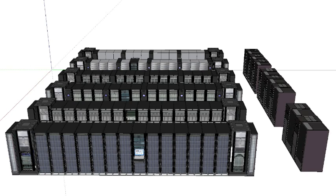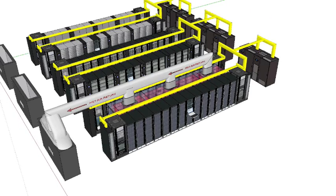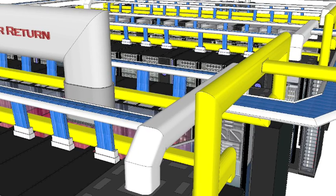Now, there are many schools of thought on this, but we often advocate that you do not need to put in a raised floor. You can run most of the services overhead and save significant cost and also improve your airflow by not putting cabling and air under the same plenum space on a raised floor. Same with the data runs. So you can use a Whalebone system. At Cisco, we primarily use a Whalebone system for data runs and power overhead. And as you can see, it looks very clean. And it's, in fact, very easy to troubleshoot a cable that way because you don't have to be pulling up tiles. You simply hop on a step stool.